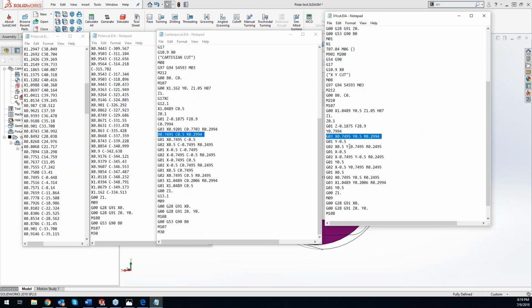So yeah, if you don't have the Y or the X-axis travel, and a lot of mill turns don't, I think a vast majority of them, you might get a half inch in negative X, which by the time you factor in the radius of your end mill, you start running out of travel real quick. Then you really need to start looking into using that C-axis rotation if you have it.